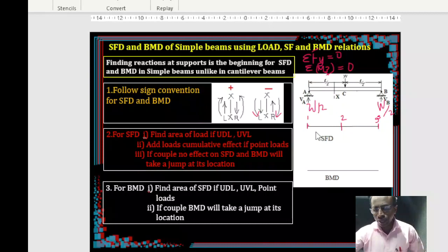Okay. So if I want to get the shear force at point 1, it is nothing but whatever forces are acting here, you just take those forces. For example, the reaction here is W by 2. The shear force is nothing but the algebraic sum of the vertical forces. So this is a vertical force, and the shear force here will be simply W by 2, right? W by 2 is acting upwards. So when you are on the left of the section, upwards is positive. So on the upside you can draw a value of W by 2. Okay, let us write this one here.